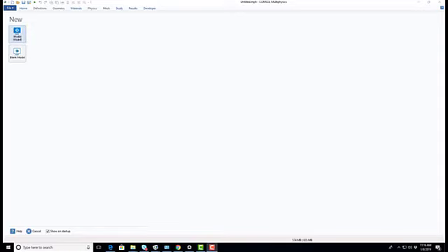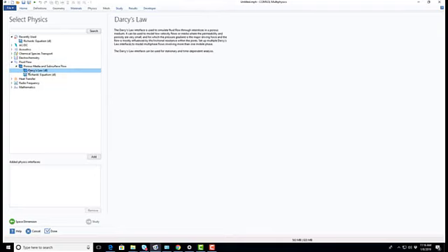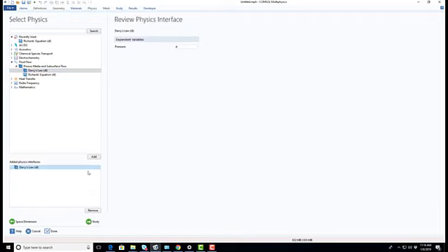So if we start off with the model wizard, then we select 1D. So we want a 1D model, and then we need to select the physics, and the physics will be flow through porous media. So we go to fluid flow and select porous media and subsurface flow, and then Darcy's law. And so we'll click on that to select it, and we'll check done down here.